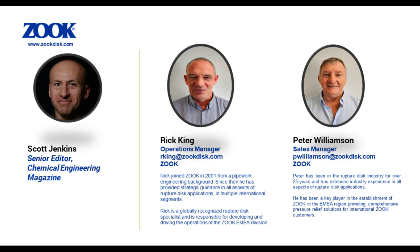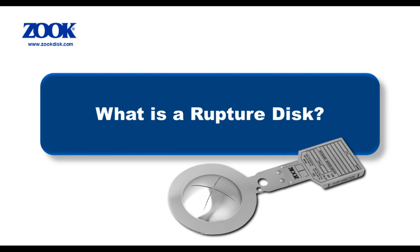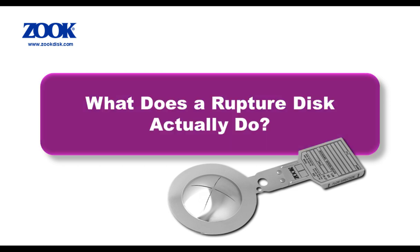Before we start to discuss what you need to know about selection, sizing and troubleshooting, we want to provide a quick introduction to rupture disks. First off, what is a rupture disk? A rupture disk is primarily a safety device for pressure relief. Because of the very many ways pressure systems are designed and applied, the disks are also custom engineered to protect plant, personnel and equipment from unplanned or unexpected overpressure. In short, the disk is designed and specified to prevent plant from blowing up. It is generally a one-time use part using a calibrated thin diaphragm designed to rupture or burst at a designated pressure.